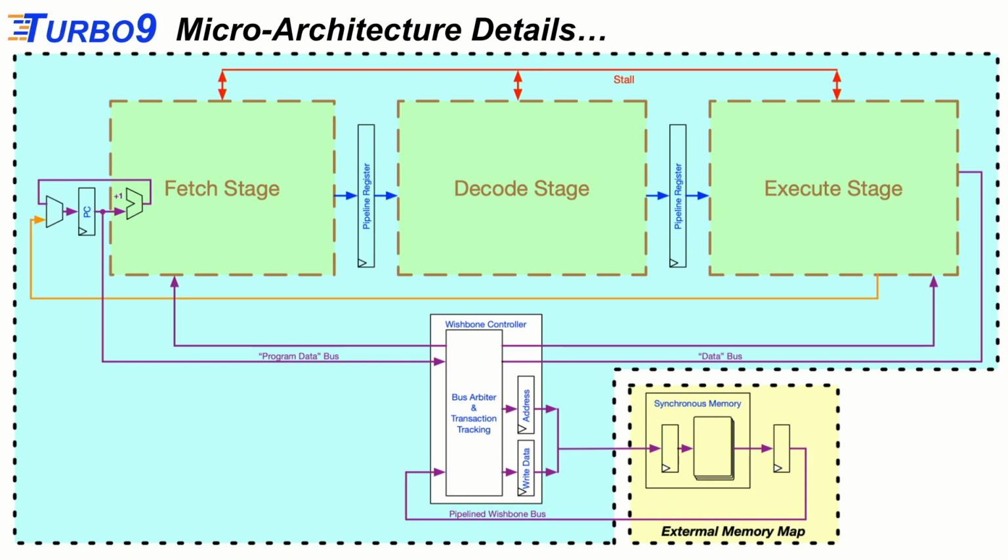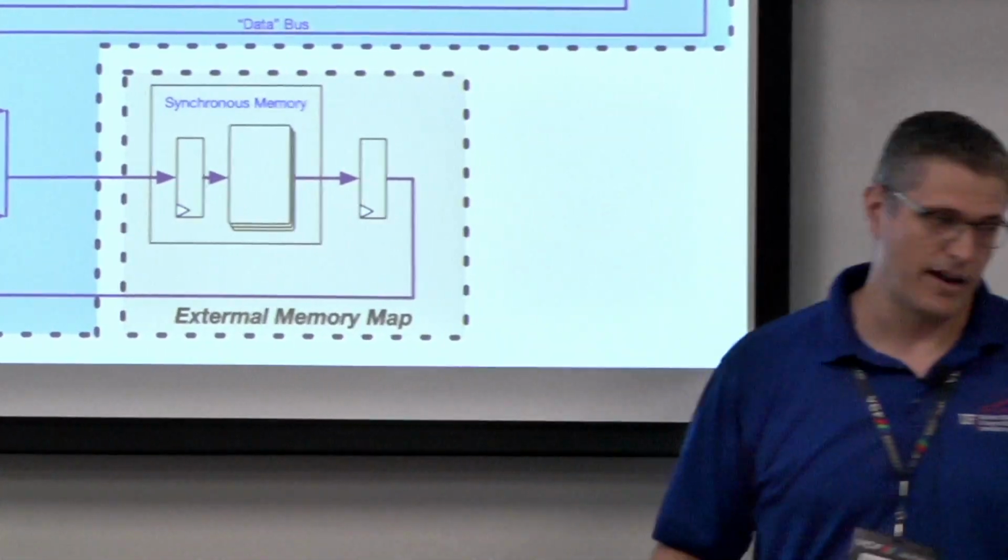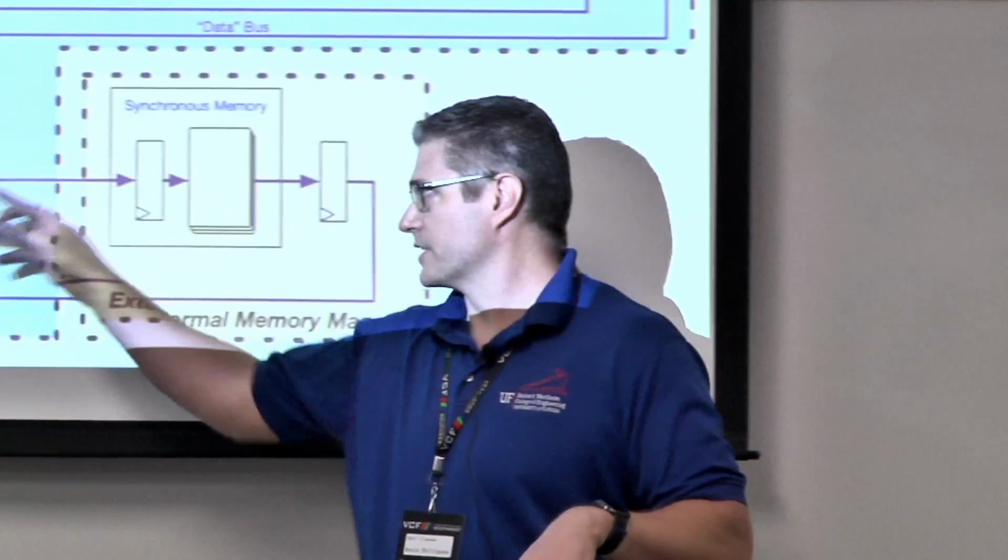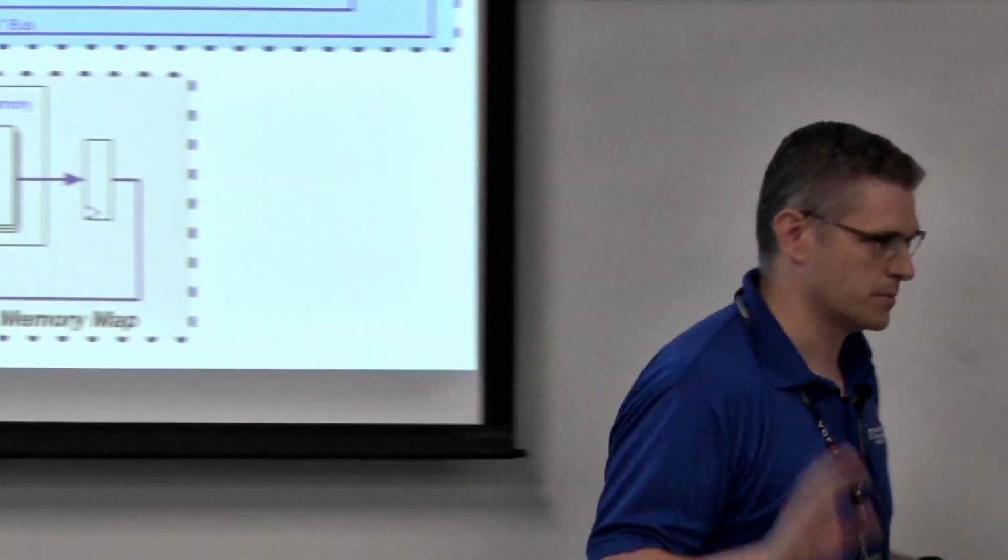And you'll notice that this bus arbiter internally has what's called a Harvard architecture, so you have a separate program and data memory bus. And then externally, it's von Neumann. Now, I've actually created another bus arbiter that is Harvard externally as well, so you can double your bandwidth, but that's just a side note.